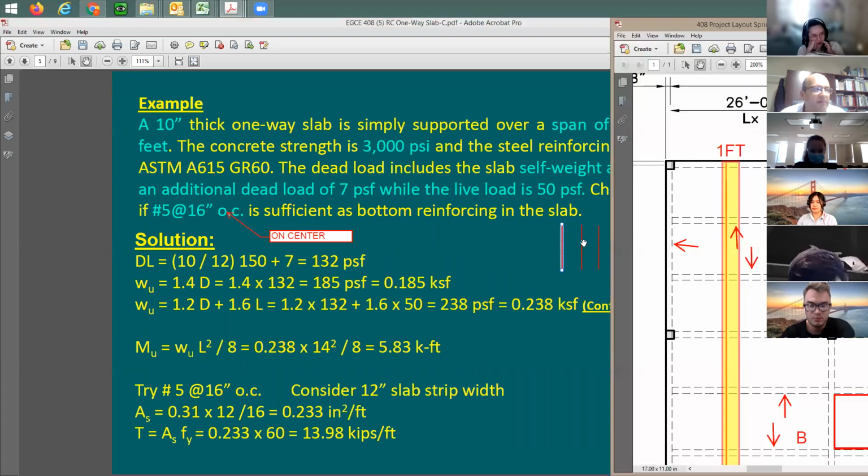Like when you go here, it's going to be the rebars, right? We're going to put the first one here, like this. It's going to be, of course, continuous. And you're not going to stop by just adding a couple of rebars. No, you're going to keep on adding. For each 16-inch spacing, you're going to be adding a rebar. And this is the difference between the two structural members, a beam and a slab.